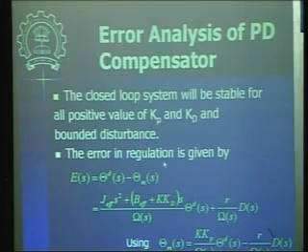So for this particular case, when we are having PD control, if we see the error in the regulation, it is given by this expression. Now you substitute for theta d from the previous expressions, or you can use the previous block diagram to see how the error at this point will look, and then you will get this expression.